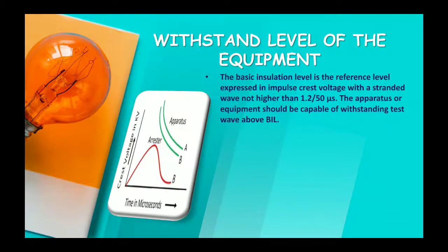The basic insulation level is the reference level expressed in impulse crest voltage with a standard wave not higher than 1.2 by 50 microseconds. The apparatus or equipment should be capable of withstanding a test wave above BIL.